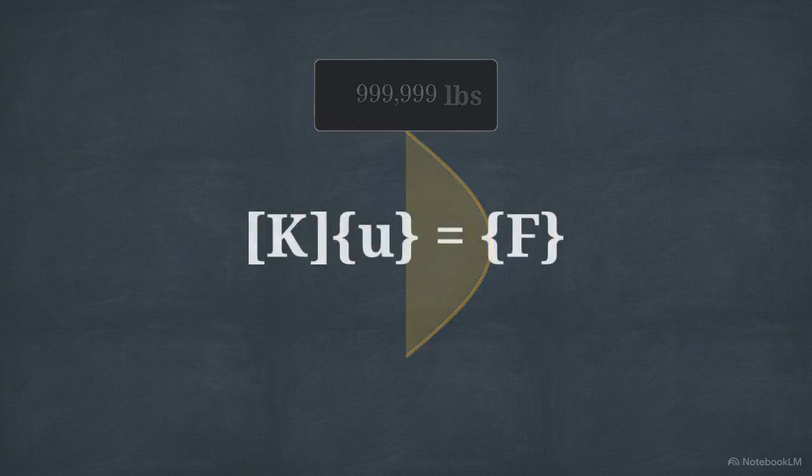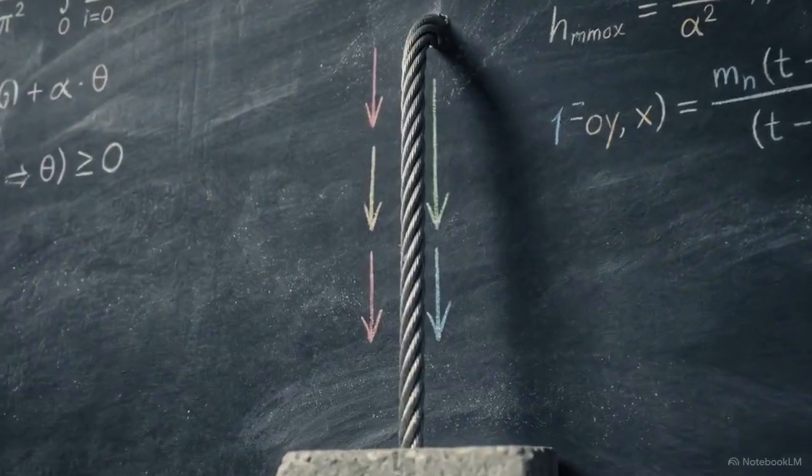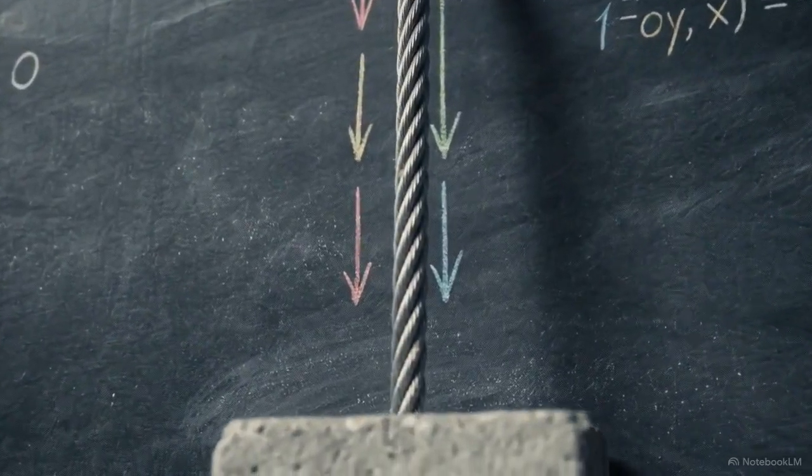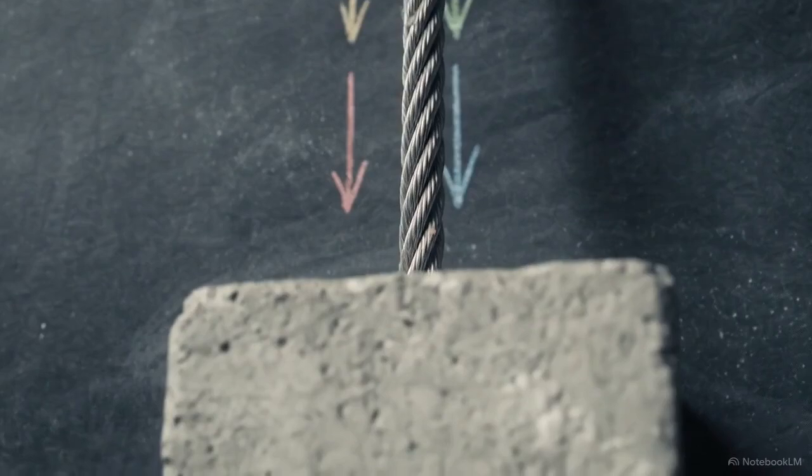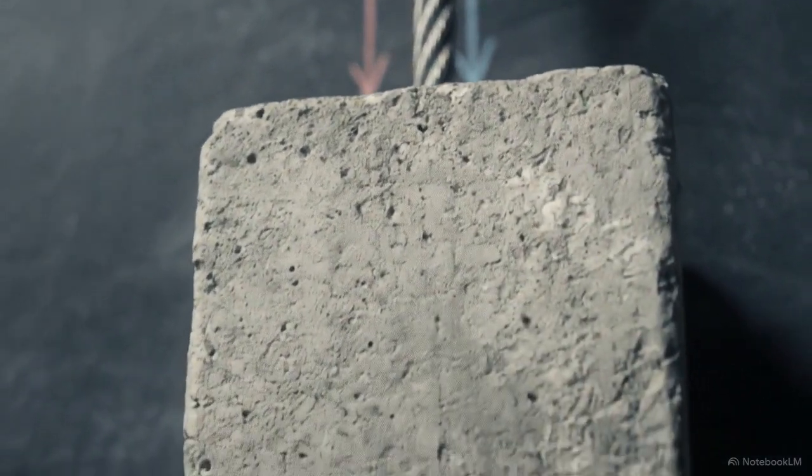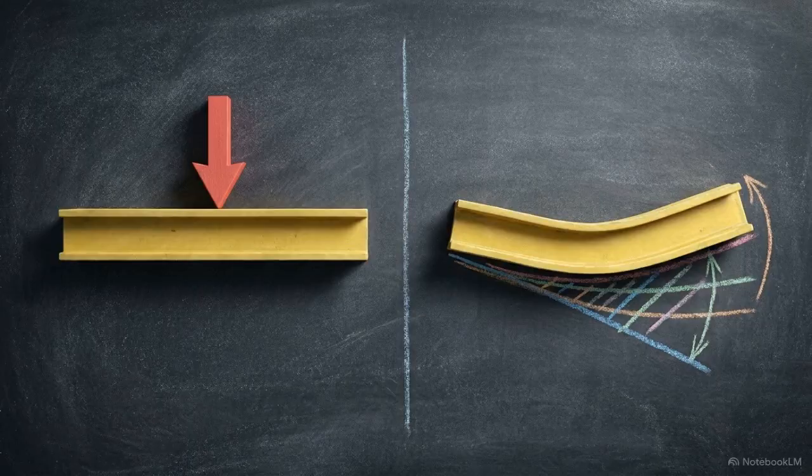This gap between theory and reality exists because the standard stiffness equation fails to account for the physical interaction between an axial force and a lateral deflection. While this simplification works for beams under tension, which naturally stay straight, it is a dangerous oversight for any structure under compression. To accurately predict this failure, we need to uncover the mathematical link that forces a purely axial load to recognize the beam's lateral movement.